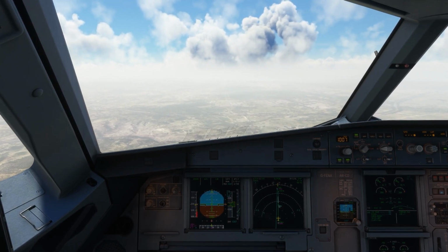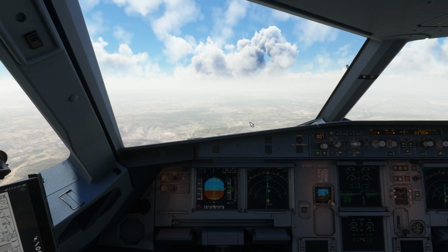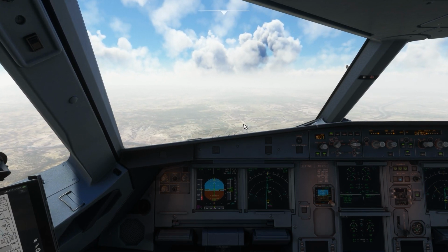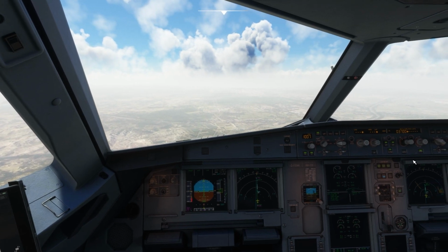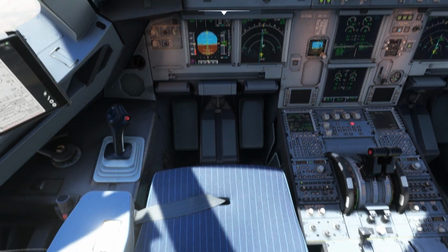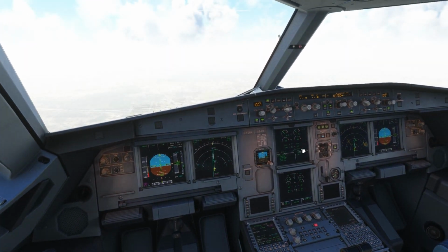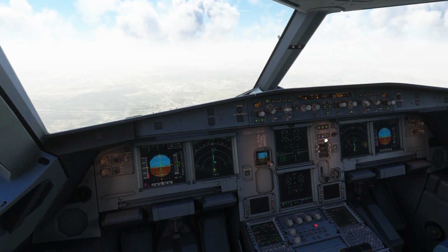Now everything is good. Now the plane and the autopilot is in the autoland position. So both the autopilots are active, approach phase is active, ground spoilers activated, flaps full, landing gears down, and the brake is set to medium.